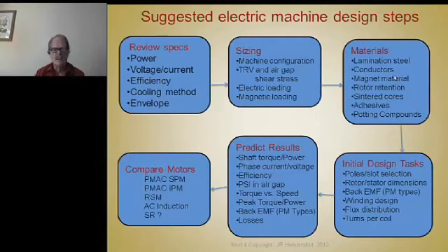You can also replace laminated cores with sintered cores. There's a lot of new materials available for magnetic materials made out of sintered parts. This allows you to achieve quite complex shapes of magnetic cores that would be difficult to achieve through a stamped, punched, laminated structure. Then, of course, significant progress has been made in recent years on potting compounds and encapsulating materials, and we're going to talk about that at great length as well.